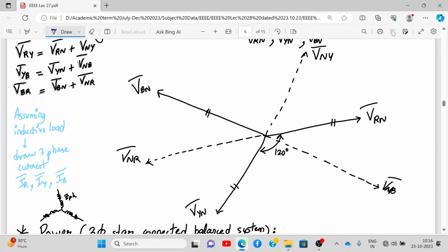Now, next, what is VRY? VRN plus VNY. That means it will be in the middle of them, by the law of parallelograms. VRN is over here, VNY is over here, so VRY will be over here. Got it? Correct? And how will you join them? Like this. Are you following? And what is the angle between them? 30 degrees, because this is my line voltage. Line voltage differs from phase voltage by 30 degrees.